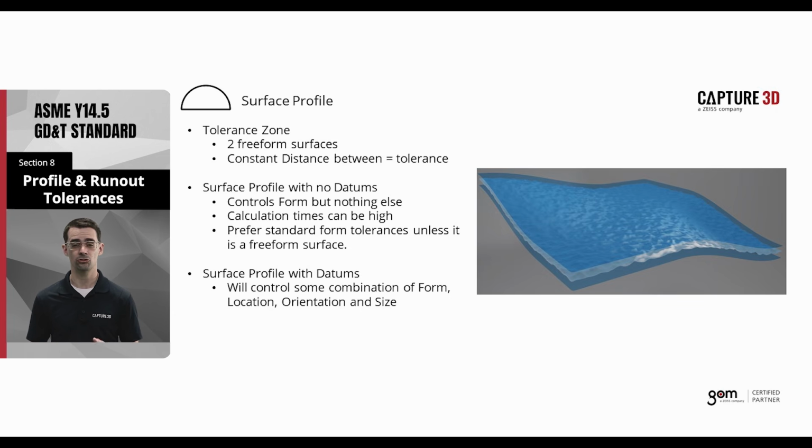Surface profile is an extremely powerful tool, but it must be used correctly. Surface profile inspections can be extremely computationally intensive to calculate and perform. What this means is that you should prefer to use standard form tolerances like flatness, cylindricity, etc.